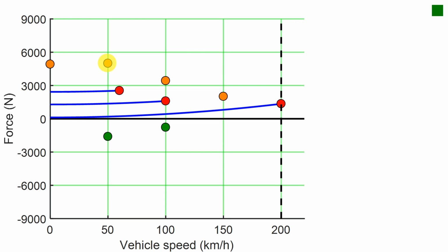Now we have reached the second step. Let's determine which requirement holds the highest force. It's 4,995 Newton and it stems from the acceleration requirement at 50 km per hour.